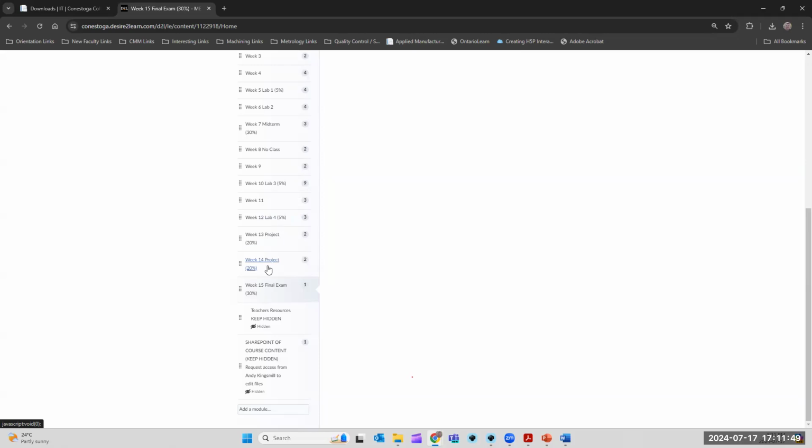It will include calibrating a new probe. So you need to make your own probe file and you need to calibrate your own probe file with all the tip angles that you need. So this is essentially starting up, building a program, building your probe file, calibrating your probe file, and it'll culminate kind of everything that we've done, and you need to do it independently with your partner.